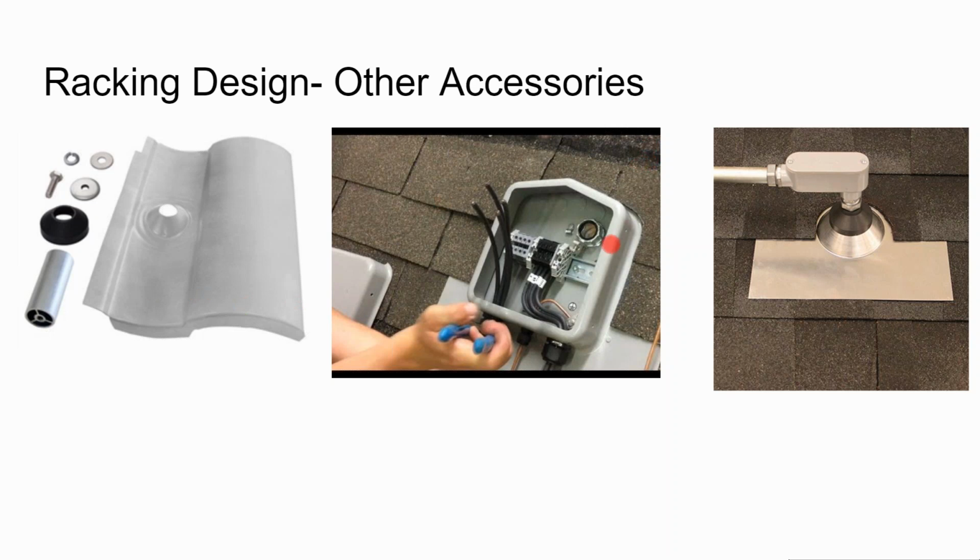For making that roof penetration, I am a big fan of going into the attic with the conduit. It looks better. There are fewer exposed penetrations. I mean, when you have to support that conduit as it runs across the roof, you're poking holes in the roof. I'd rather poke a hole in the roof that's covered up by the solar array and not be subject to so much rain. But you get specialty boxes that are made, and this is the big one.